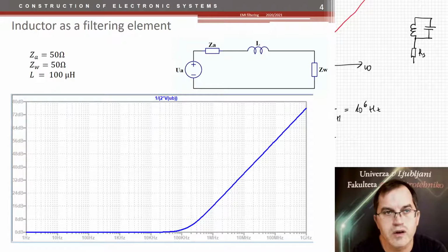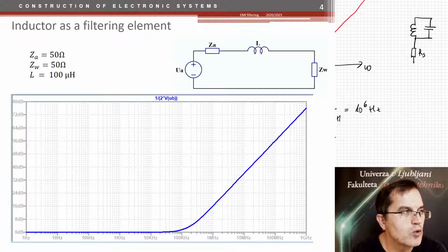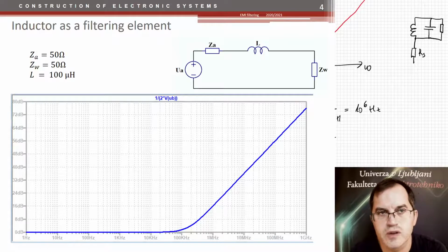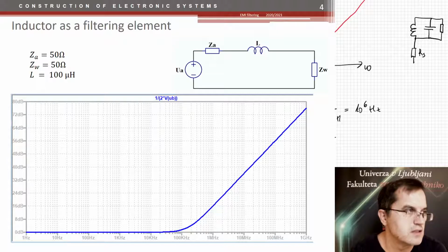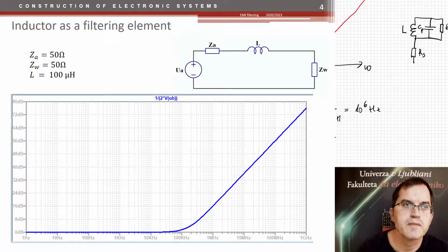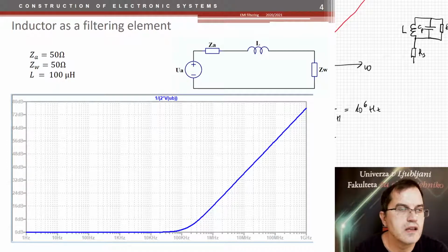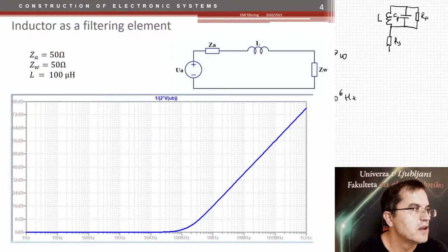If the coil is not an air coil, if it is wound on a core, a ferrite core maybe, then it includes some losses there in the core. These are 2 losses, the hysteresis losses and the eddy current losses. So this is the parallel resistance of the coil, the parallel capacitance, and the inductance of the coil itself. So all that gives another story.